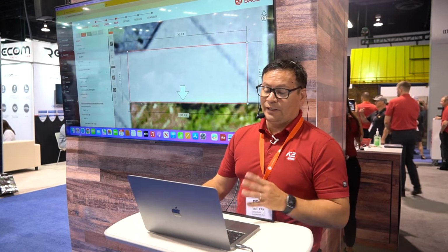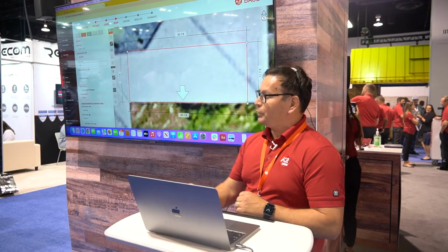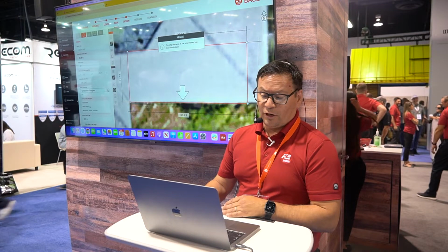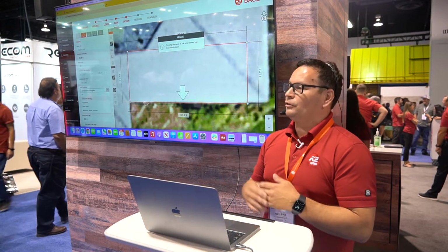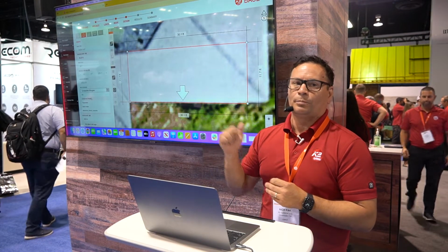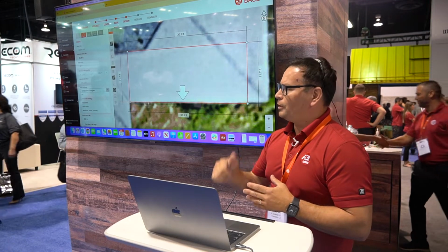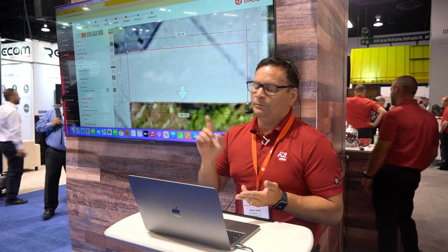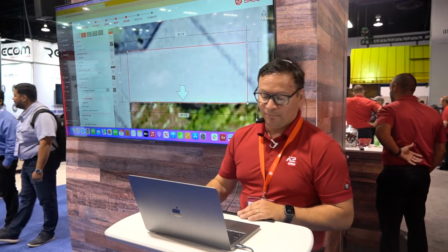If you want to select anything else about the roof, like specifically the roof pitch, this is a 22 degree roof here. We're going with composition shingles. If you did want to change the roof type, you can do it here from this menu if needed. We do offer different types of roof materials, so if you're going to be using some of our corrugated brackets or some of the newer products that came from our demonstrations today, you can select that. We offer trapezoid metal, standing seam, tile, and of course flat roofs. This is just a nice comp shingle job.